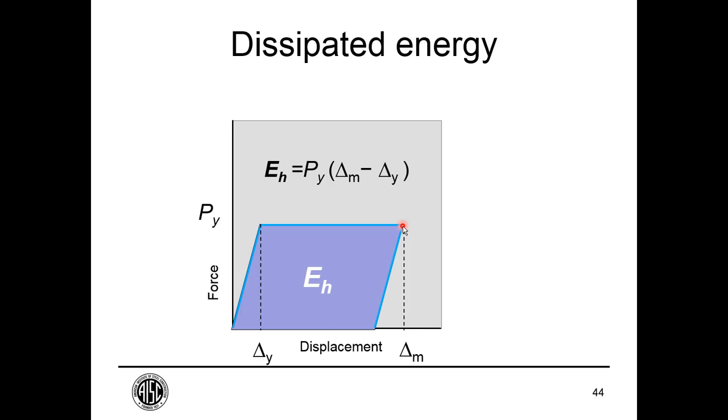And this behavior may affect a little bit the ductility in general. The warmer something is, the warmer steel is, the more ductile it is. And that's an interesting phenomenon directly related to the energy dissipated through inelastic drift.